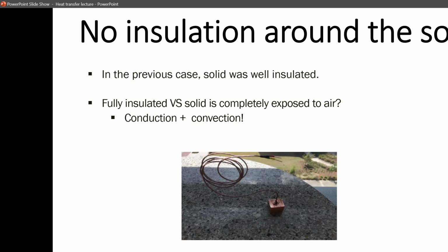Okay. The second experiment you are going to do in this lab is the heat transfer coefficient calculation for a cooling of a heated copper block. So you have this type of copper blocks. This is connected to a thermocouple. This is connected to your data acquisition device. You just put it in a pot of boiling water. You let it heat up to 80 degrees Celsius, and then you take it out.